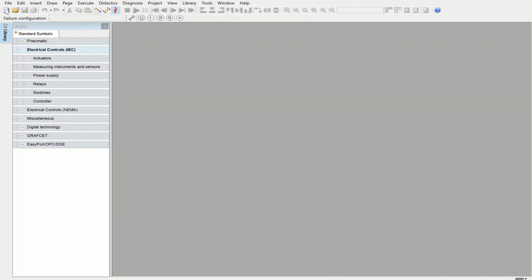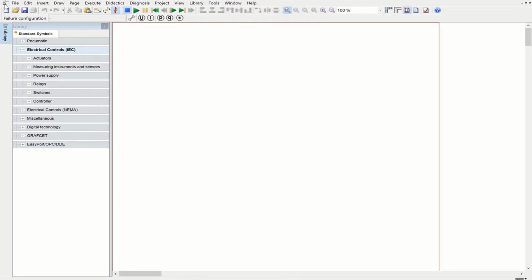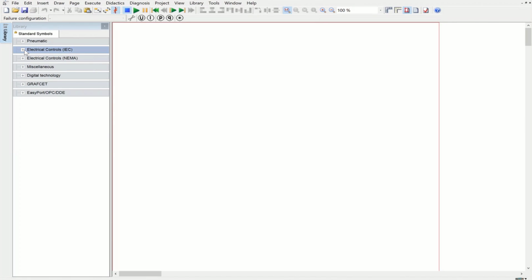So let's start with the first circuit. We had a very simple circuit in which we had a pneumatic part with a single acting cylinder, an electrically actuated directional control valve, a manifold, air service unit, and air supply. In the electric circuit part, we had electrical components like the power part, a switch, and a solenoid. So I'm going to design the pneumatic side first.